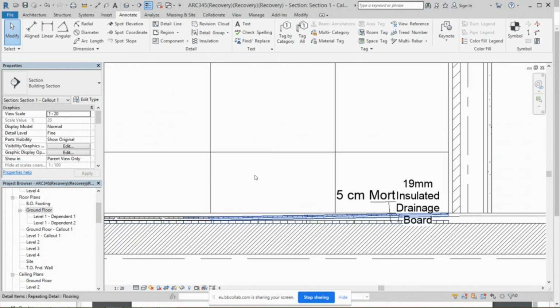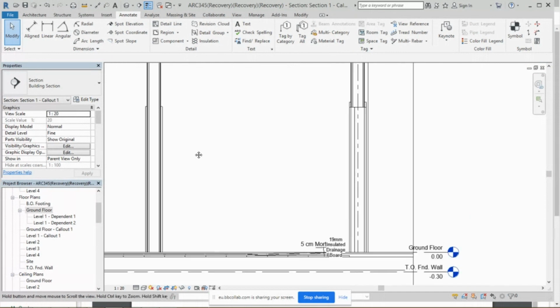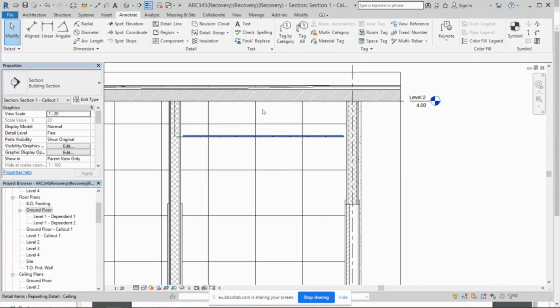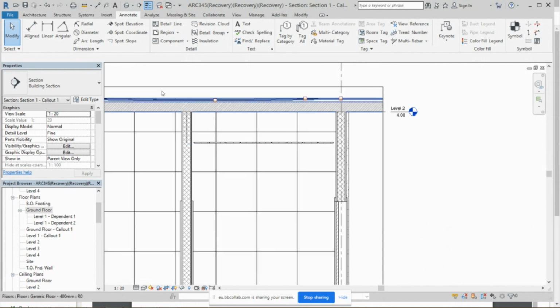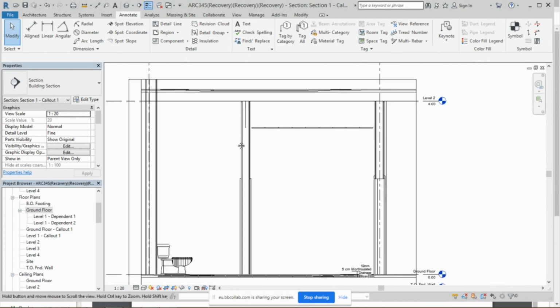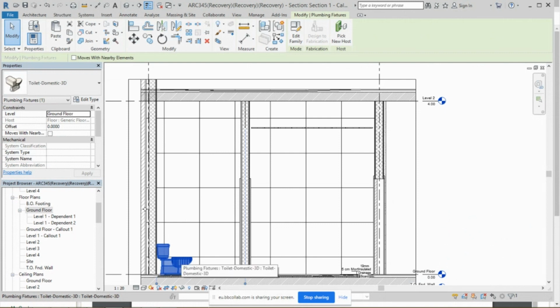for your repeated item like ceramic, and then mortar, and then the slab that is made out of concrete. So these are important items that you would show. And also, if you do have a suspended ceiling like this, you have to show it, in addition to drawing the suspended element or the suspension wire that connects this to that. So this is what is needed, plus the fixed furniture, fixed elements that should be shown in here.